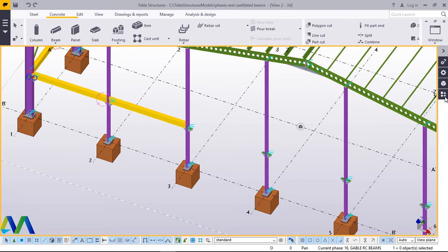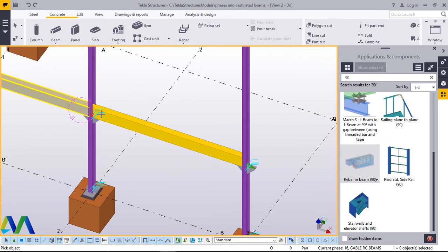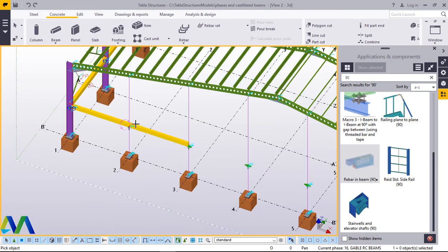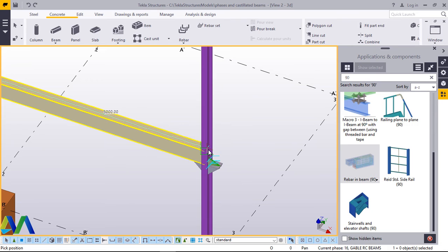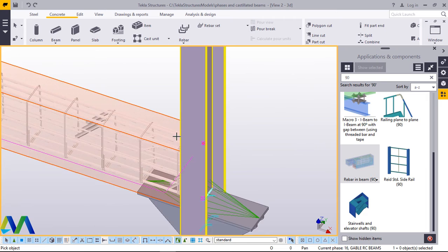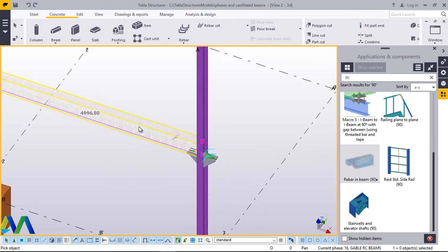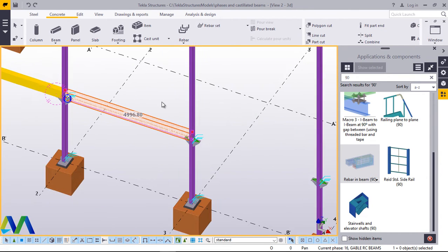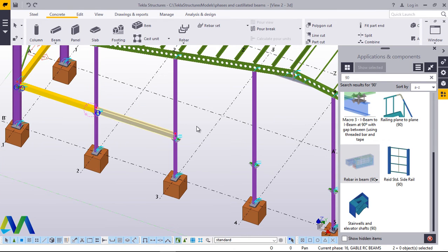After doing all this, come to applications and components, pick Rebar, and now just go straight to Rebar Placement. Snap right there, snap right there, pick the positions. Remember the settings remain the same for the rebars. And remember these are also the same. We'll just select that,